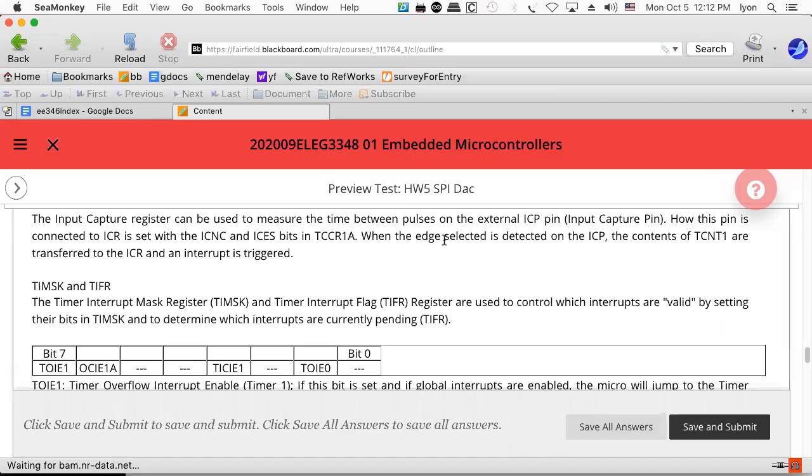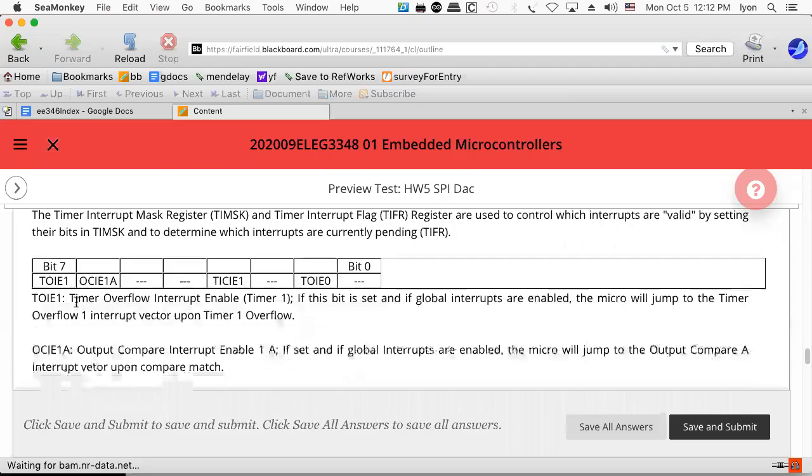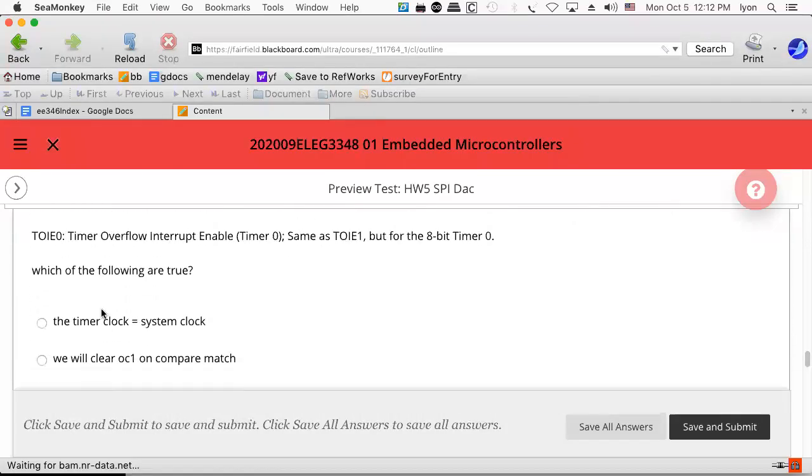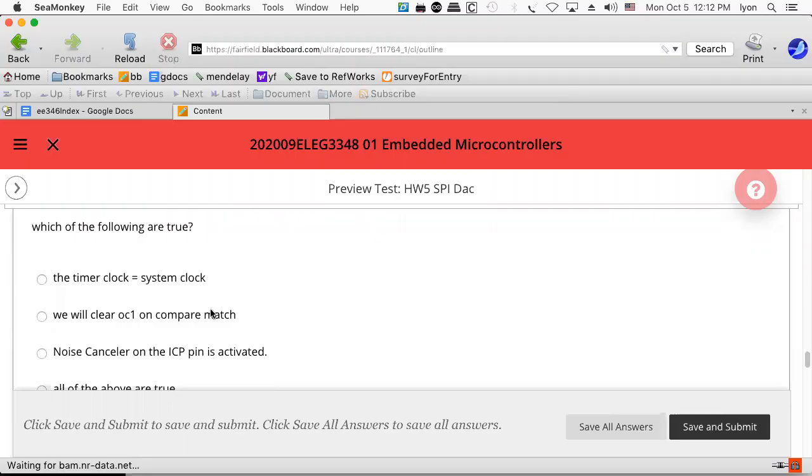So the timer can be used as an internal timer or an external timer. If it's used as an internal timer, we can scale what the timer is responding to, and then it can generate an interrupt. So the whole point, what's the point of this? You're going to create a timer that's going to generate an interrupt that's going to allow you to output a signal to the pulse width modulation output system. Let's see why we would need something like this.